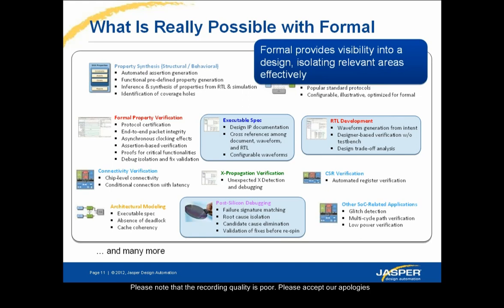Anyway, the other one is, again, on the bug analysis side, we have some support for what we call post-silicon. It doesn't have to be post-silicon. It could be prototype type. But one of our customers actually debugged, this figure always sounds absurd, but I think it's a 190 million gate design using formal. They had a complex failure in silicon, and they actually loaded the whole thing into a fairly monstrous computer.